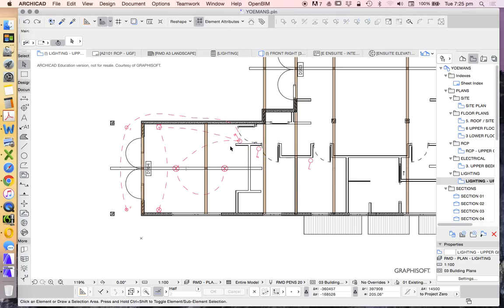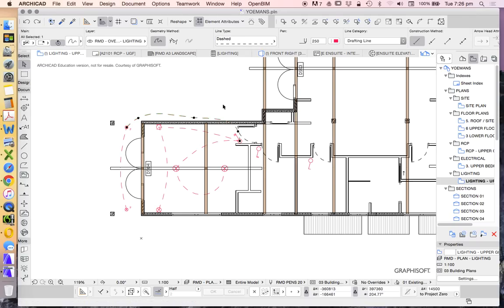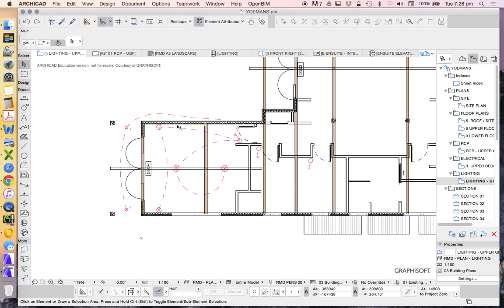I like using red. I've talked about this a bit. I know it's not Australian standards. I apologize if I'm misleading people. I like using it because it's much easier for the electrician to identify. It's much easier for me to identify in the plan, but most importantly, if it's printed in black and white, it still works, and that's the most important thing. I don't need it to be red. The red just hopefully makes it a bit more identifiable.